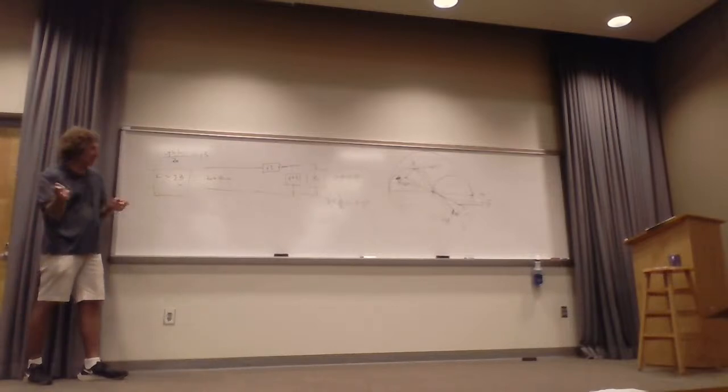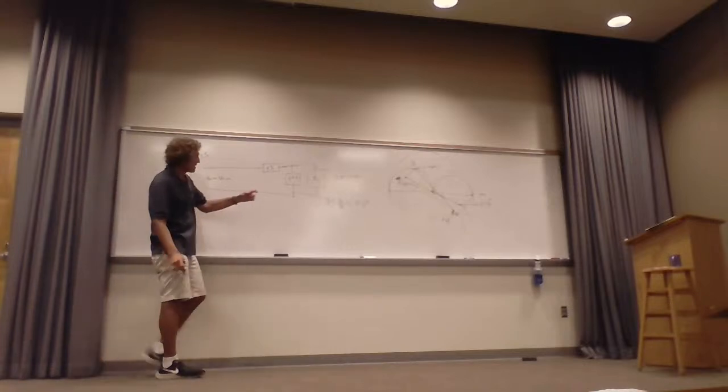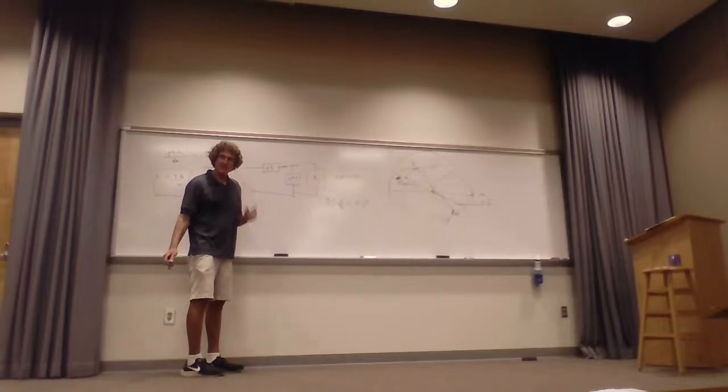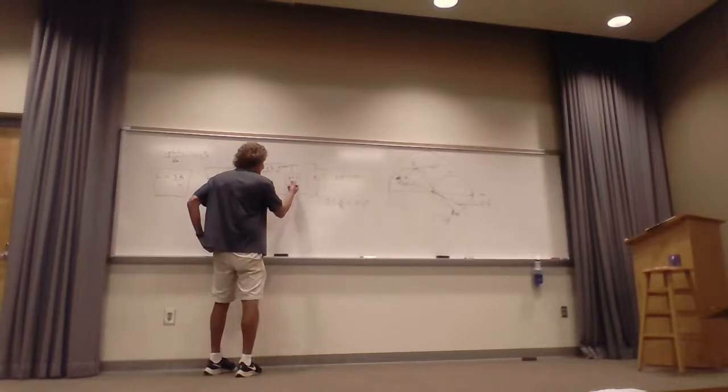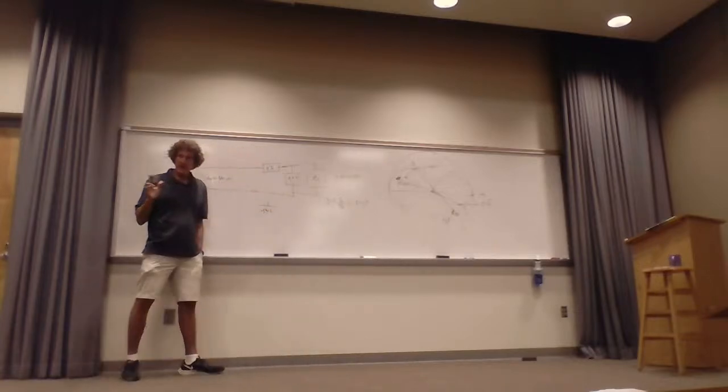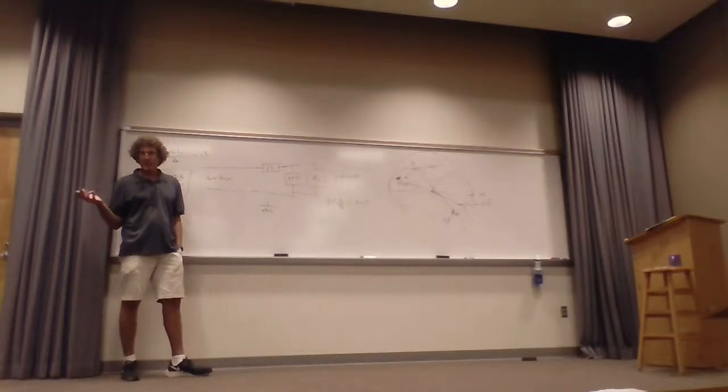All right. Now, how about over here? That's an admittance, right? Here's the way I do this for you guys, because a lot of people don't use the admittance stuff at all. I know that for a capacitor, the capacitor has an impedance of 1 over j omega C, right? Do you all agree with that? Now I'm going to normalize it.